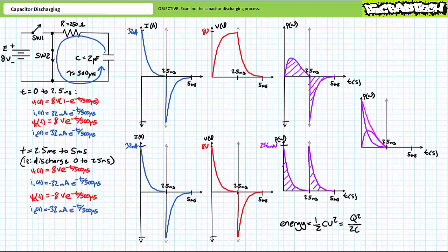In conclusion, we examine the capacitor discharge process. We learned a discharging capacitor can supply a burst of outgoing current, which then decays to 0 over 5 time constants. Voltage across a discharging capacitor drops from the previous charge value to 0 over 5 time constants. Current through the discharge path must equal the current out of the capacitor, and all voltage must be dropped across the discharge path.